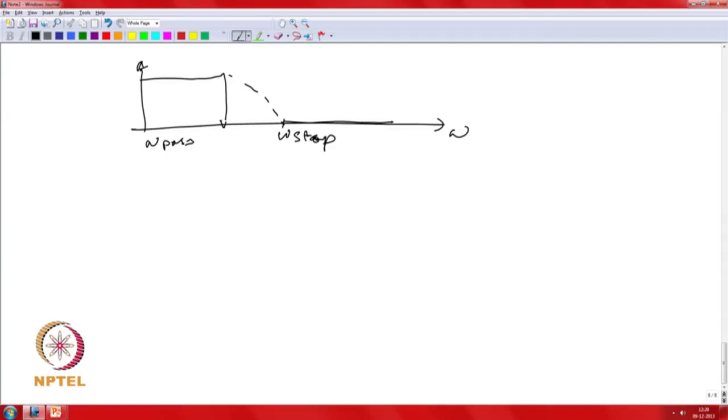So the question is, what belongs to your pass band? You would definitely have the fundamental frequency in your pass band. You might have, say, your fifth, seventh harmonic, etc.